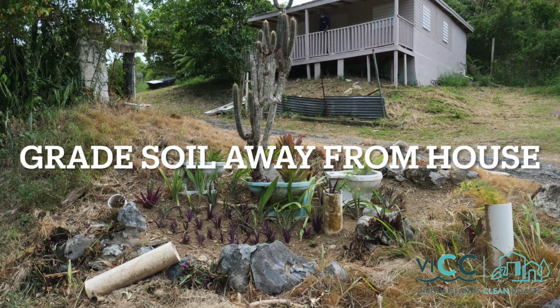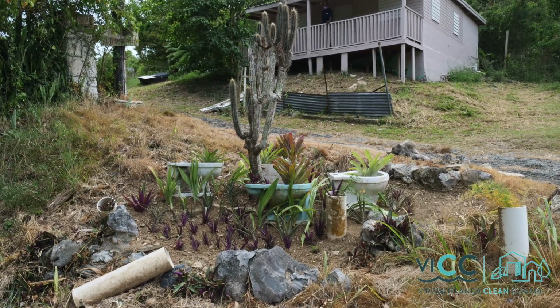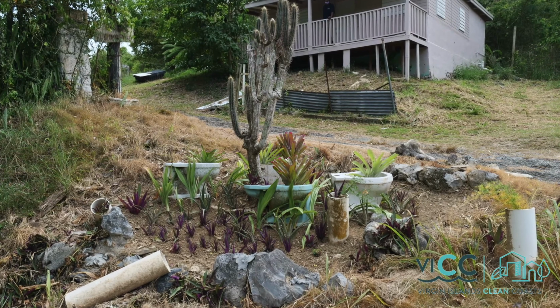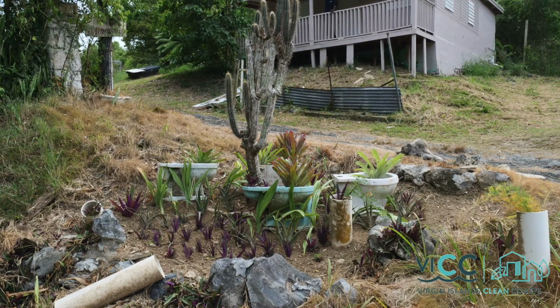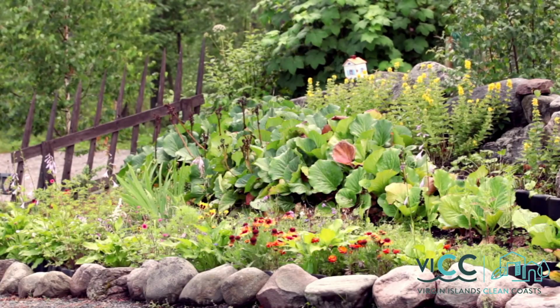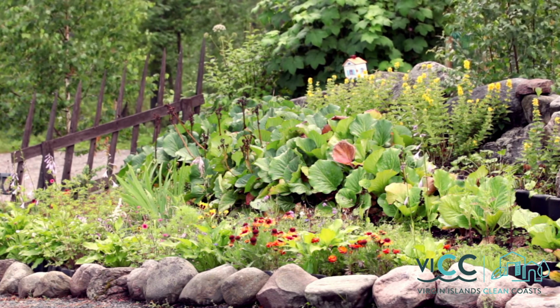Grade soil away from house. Soil should be higher at the foundation and slope away the first 6 feet. A good rule of thumb is 1 inch drop over each foot. Add soil along the foundation as long as it remains 6 inches below the siding of the house.